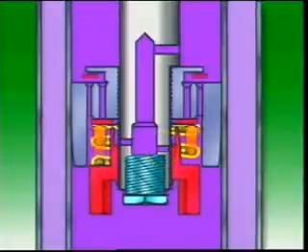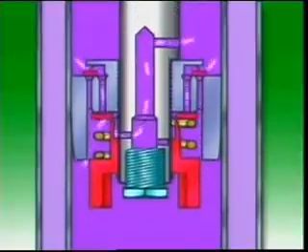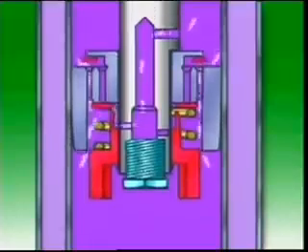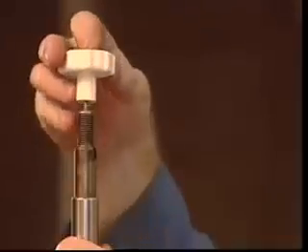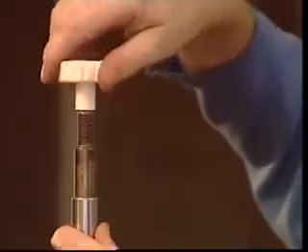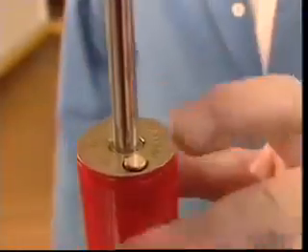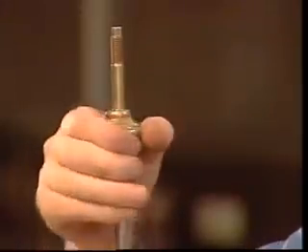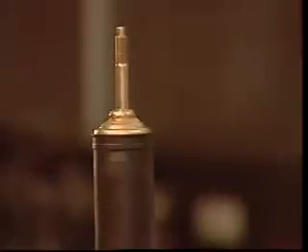Closing some of the orifices and increasing the spring force applied to the valves makes it harder for fluid to flow through the piston. This increases the dampening effect of the shock absorber. The method of changing the position of the valve varies. On this model, it is adjusted by a spindle that reaches down inside the plunger. On this shock absorber, when it's extended to its maximum length, a pin is depressed, locking in an adjustable slide on the piston assembly. Twisting the two halves of the shock absorber changes the number of orifices and the spring force on the valves.